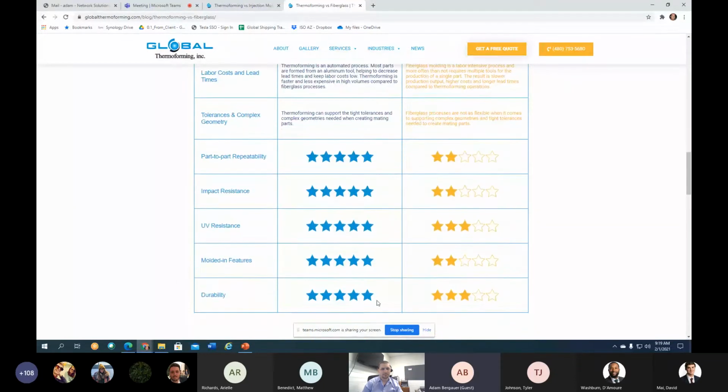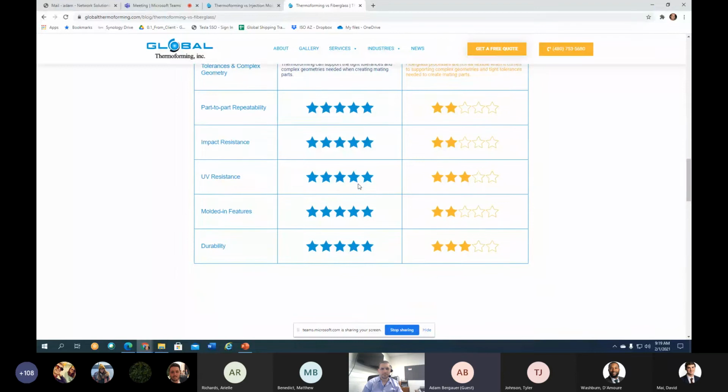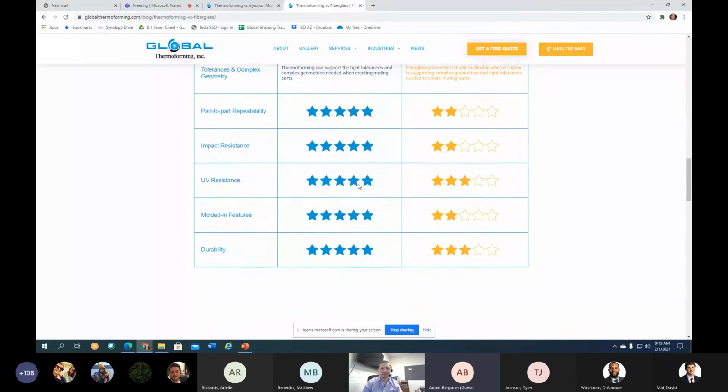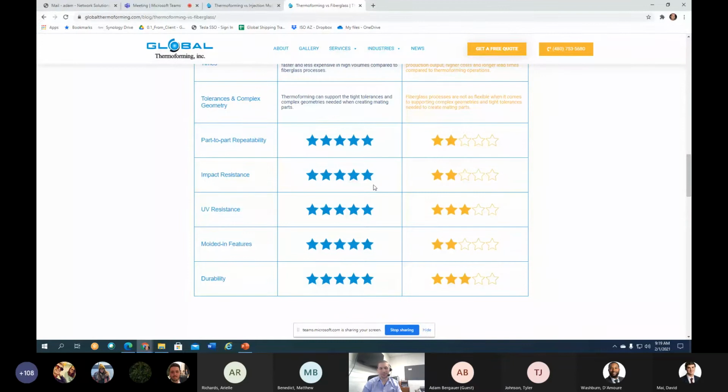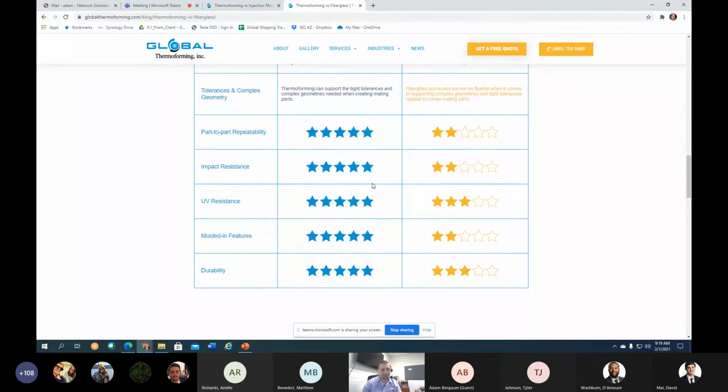And then you can see down here, these are some of the strengths. Obviously, I don't list any of the weaknesses in thermoforming, because you're trying to sell to the world. Right. But those weaknesses might include things like limitations on the thickness control. High volume production, super high volume production might be a problem. Cool. Interesting to know and understand those things.